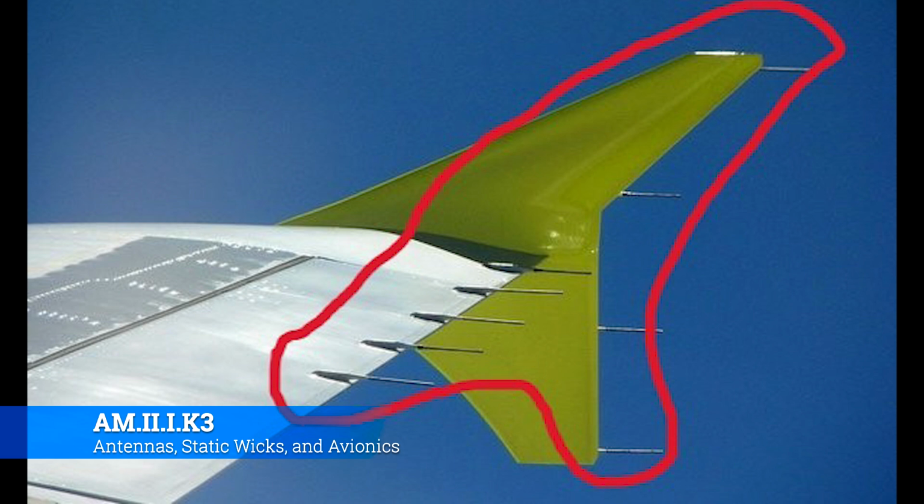When you're sling loading with helicopters, part of the operation is to ground the helicopter. You take a big, like, it looks like a shepherd's crook that goes to a grounding rod, and you touch the helicopter, so that all of that extra static electricity can come off of the helicopter.